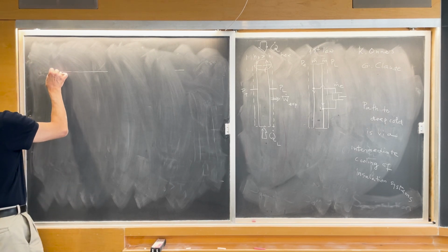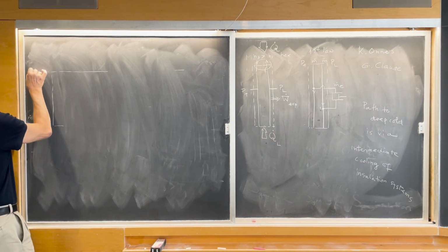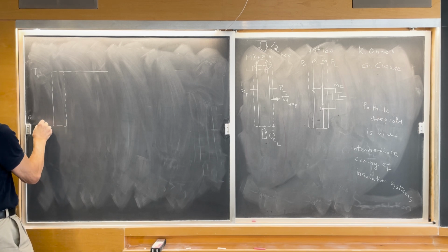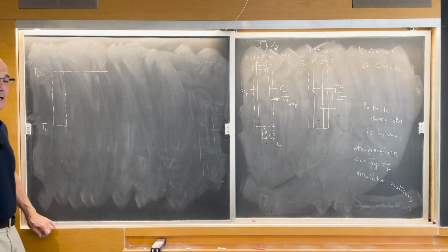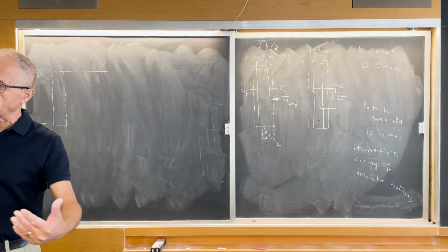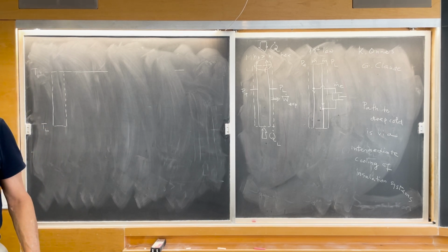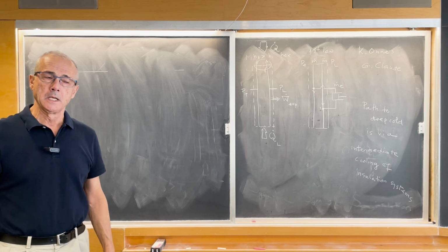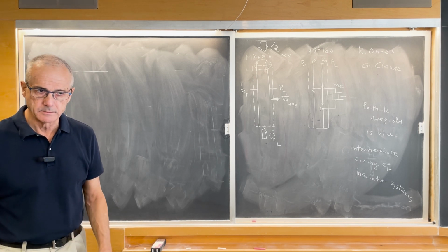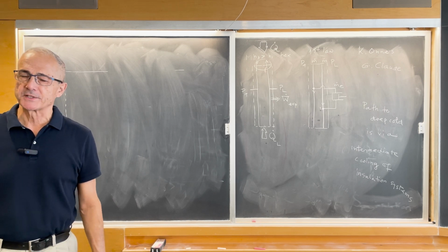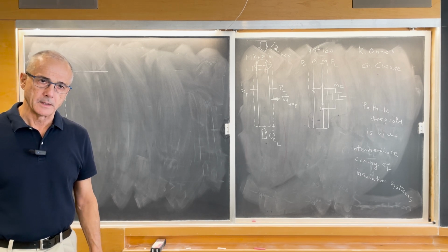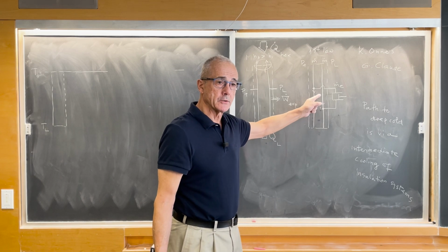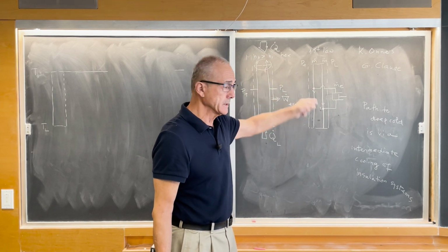I told you the one below T0 is the cold zone, and the cold zone houses everything, including the insulation of the machine. That was the message of my first 10 minutes in this hour. That insulation has many pieces of hardware. One is the counterflow heat exchanger, this one, which I showed you how to provide with intermediate cooling.